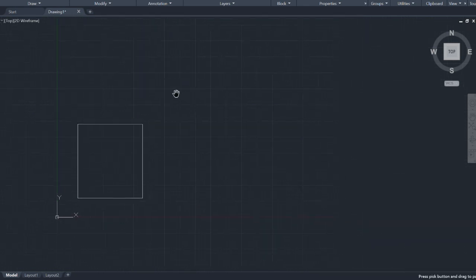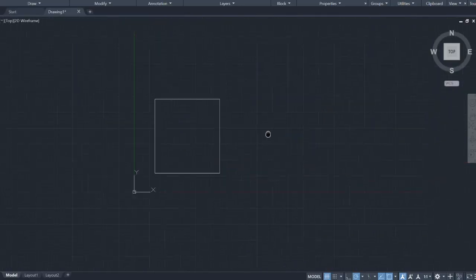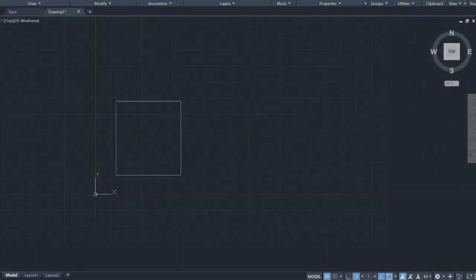And you have a pan. And you're going to use your left click in order to move your drawing. And there is also a shortcut of this one. So if you have, again, a scroll wheel on your mouse, just click on that scroll wheel and then it will automatically pan your drawing. Okay? It can move in whatever direction you want.